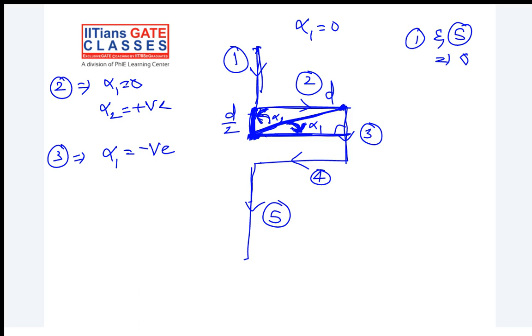So this is D and this is D by 2. You can calculate the hypotenuse. Similarly, what about alpha 2 here? Draw a line from the end point to the observer and your angle will be towards the radial line. This time you are going anti-clockwise or clockwise? You are measuring alpha 2. Anti-clockwise, so it'll be positive. Anti-clockwise means positive. So you can do the same exercise, do the trigonometry and find out alpha 2.